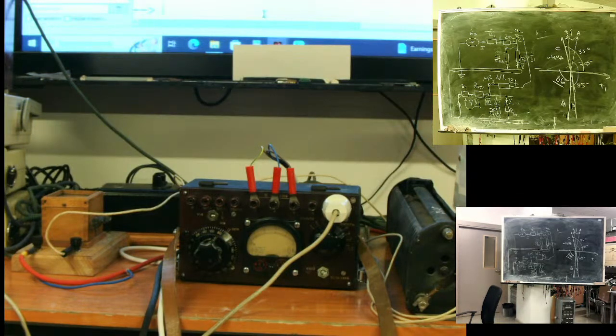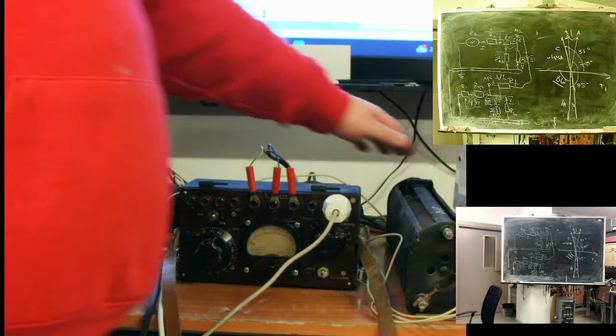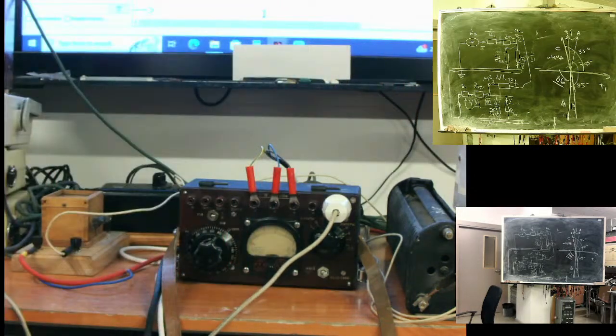You see? It's on the primary side. I have one big current in phase B and two smaller, approximately 1/2, in A and C. What's going on? What kind of fault do we have? B, C. But on the primary side, we see something closer to B to ground, yeah?